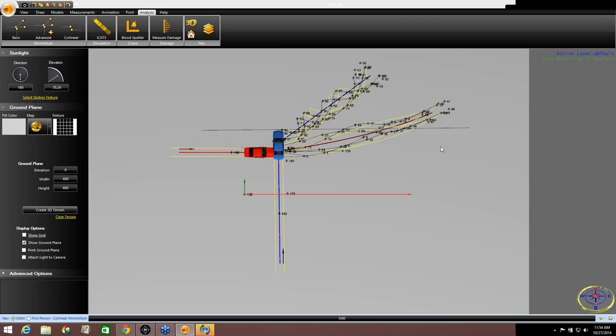Sometimes the damage of a car will lock a wheel down. Then you know that you have 100% braking on that wheel, because that wheel's not turning anymore. It's totally locked. The damage has got it locked down. Sometimes the front of vehicles get damage locked down, because when they hit another car, they get crushed back and now they can't move anymore. You can assume 100% braking on those two wheels. Any other questions?